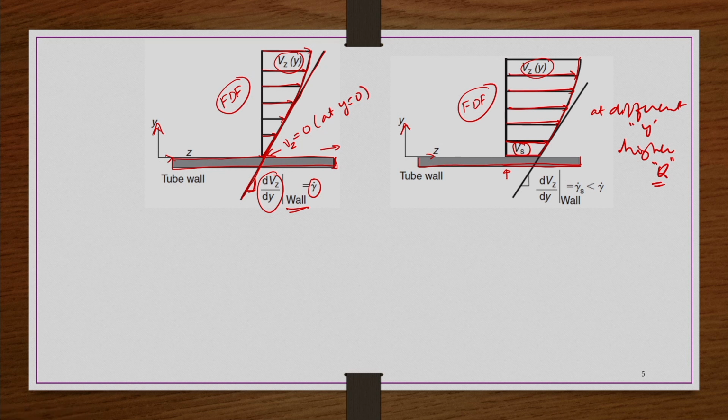Whatever the flow rate you expect when you take no slip boundary condition, as in the previous analysis, you have all the equations, so without doing experiments also you can get a certain kind of value. So, that should not be an issue, right. For a given pressure drop, compared to the velocity you expected, you get higher velocity or higher flow rate if there is a velocity slip at the wall.